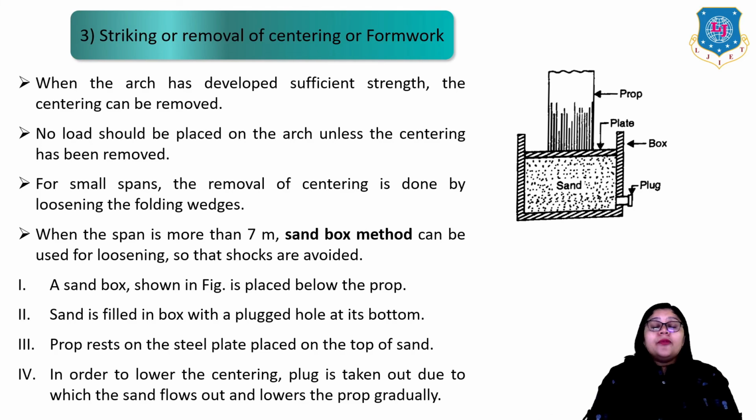For this method, a sandbox, shown in the figure, is placed below the prop. Sand is filled in the box with a plugged hole at its bottom. Props rest on a steel plate placed on top of the sand. In order to lower the centering, the plug is taken out, due to which the sand flows out and lowers the prop gradually. Here you will get a clear idea from this image of the sandbox method.